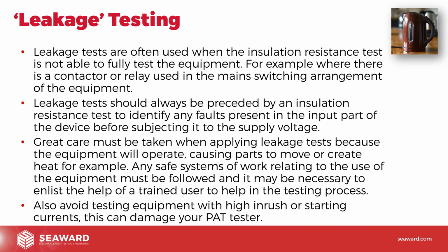But always think about the safety when you do mains powered tests, because it can be a big problem. I mean, particularly something like a kettle, for example. If you haven't got water in there, the element's going to glow red hot. And I've seen loads of people who've still got the crocodile clip clipped onto the element from doing an earth continuity test. They go straight into the leakage test, turn it on, and it melts the crocodile clip to the element inside the kettle. There's a load of smoke and burning smells, and it's not very nice.